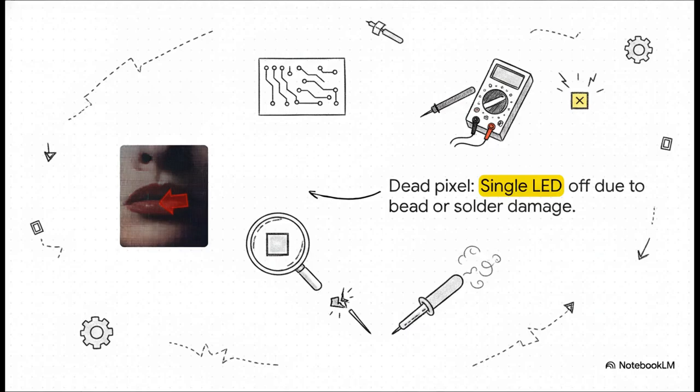But here is a massive pro tip straight from the manuals. When you test that newly replaced pixel with your multimeter, you have to do just a quick touch. Your multimeter generates a small voltage to detect a closed circuit, and holding it on there too long can actually overdo the current. You could literally burn out the exact LED you were trying to test.